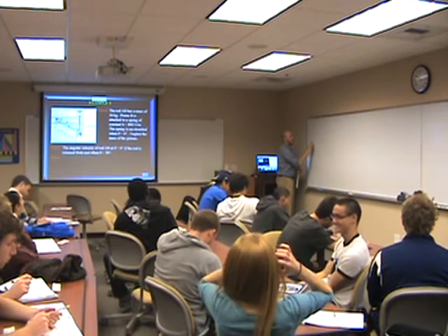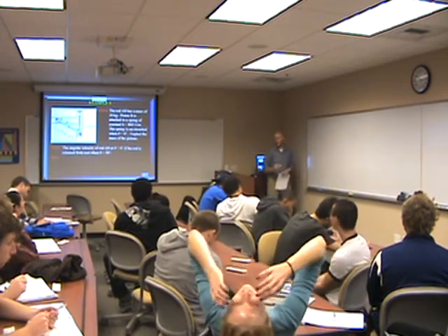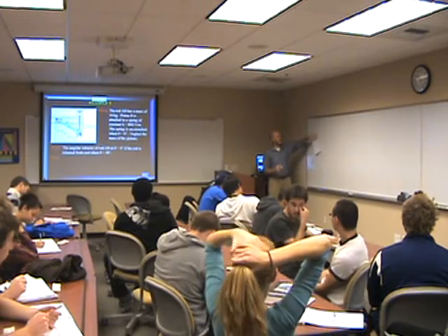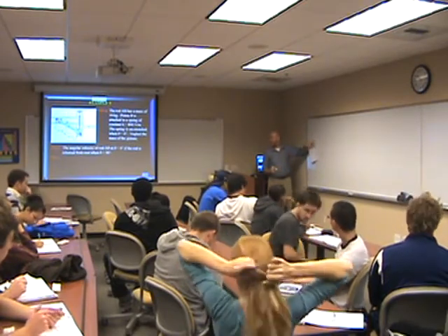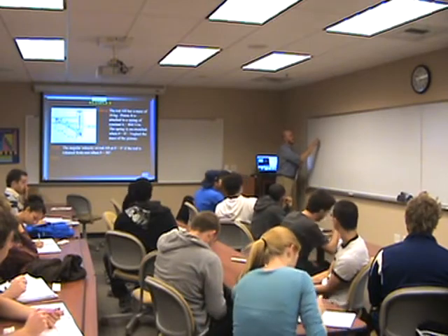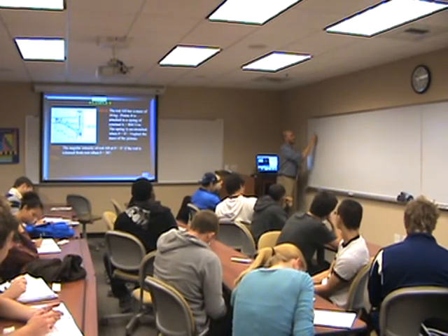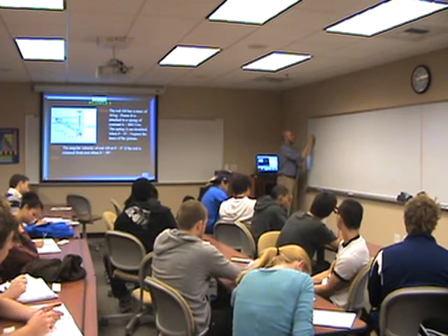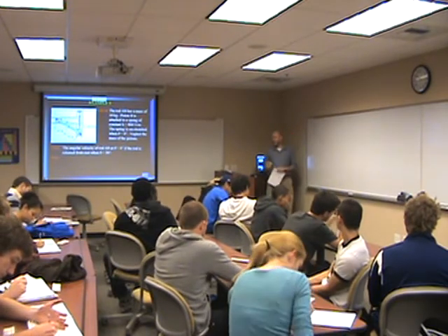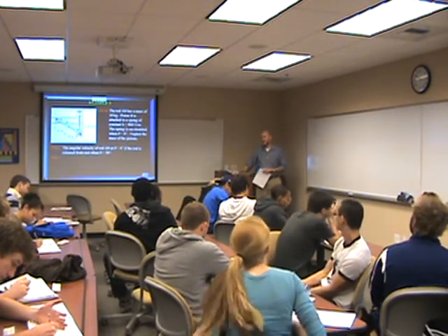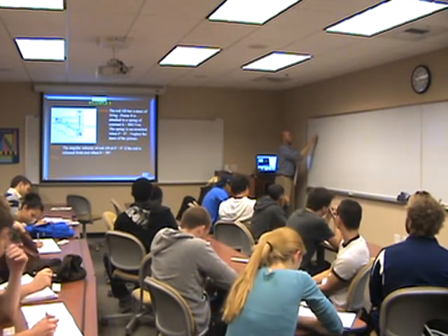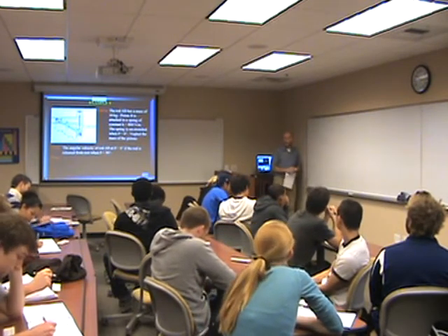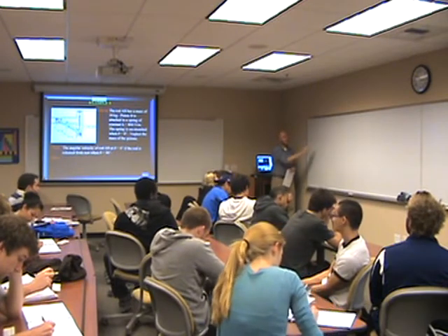So here is our instant center. At this instant, this block is rotating about this point right there. This is 0.2 meters, this is also 0.2 meters. How far away are we from the instant center? We are 0.2 meters. It's similar triangles.